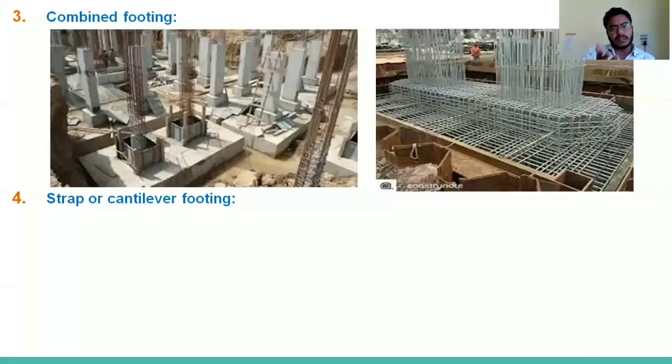We do not go for combined footing, as compared to the strap footing, in two cases: where the bearing capacity of soil is relatively high, or where the two columns are really far apart. In that case, you will see the strap or cantilever footing is more economical.